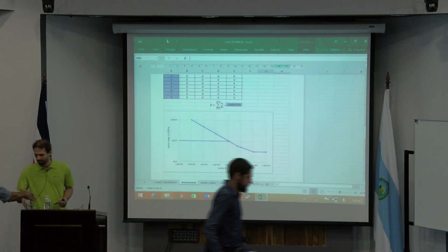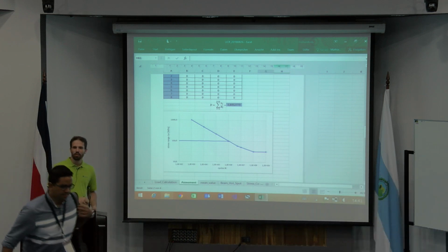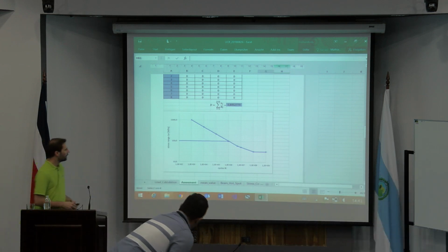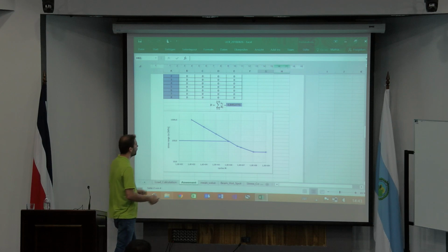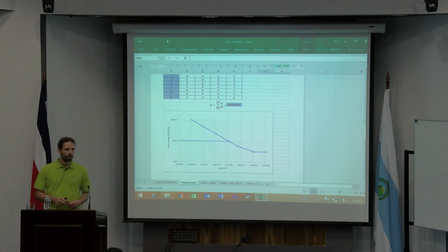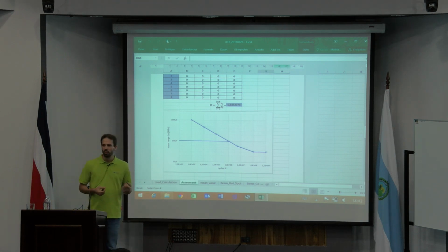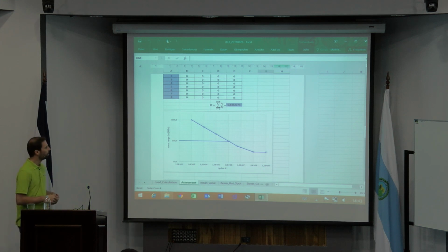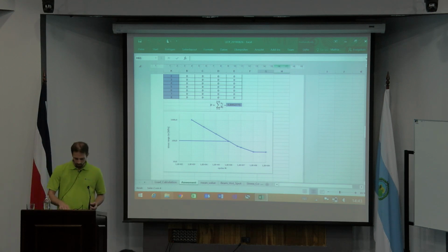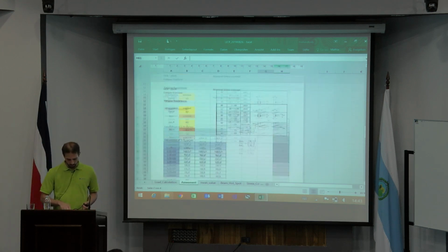Good morning. We could do the first fatigue assessment, and as you can see here, with the 100 MPa and the 8.55 × 10^5 cycles, we got a fatigue damage due to a linear damage accumulation of 0.84.